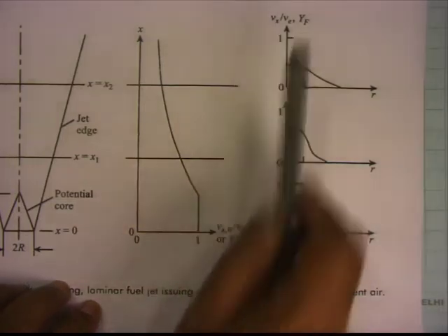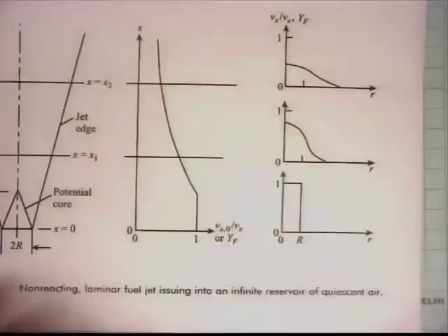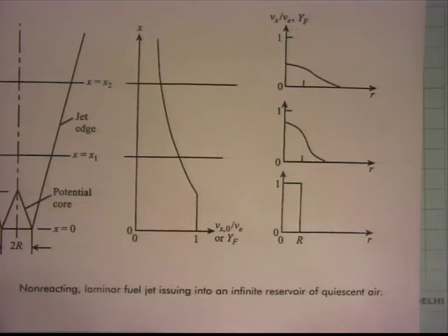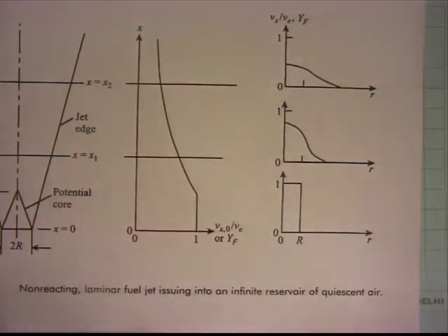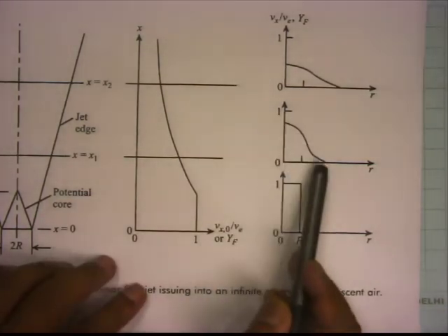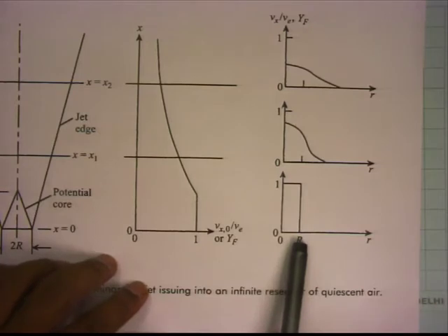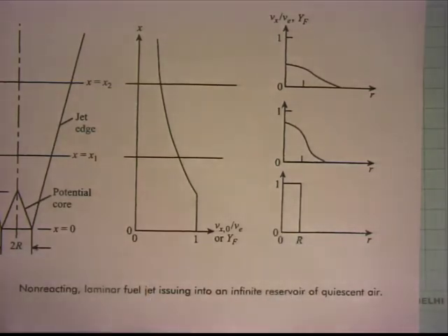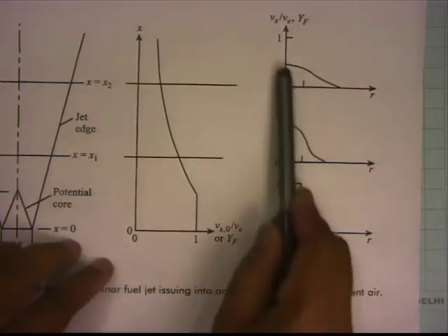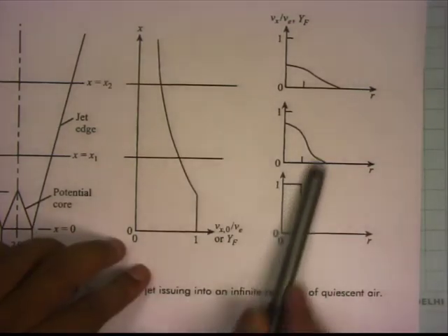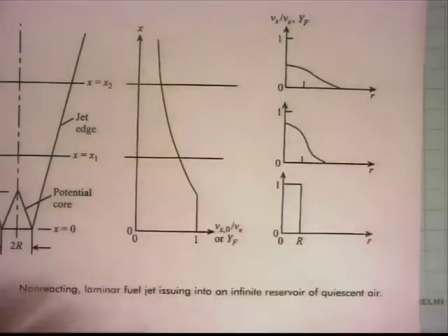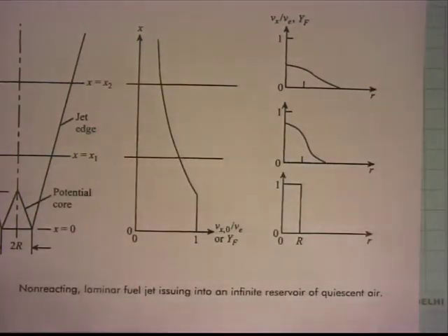And then if you go higher and higher along the height of the flame, you will get a decay in the center line velocity, and also the velocity profile gets rounded. It's not a sharp top hat profile like what you get at the exit of the nozzle, and it keeps expanding. So if you just mentally add these, you will get the jet contour, isn't it?